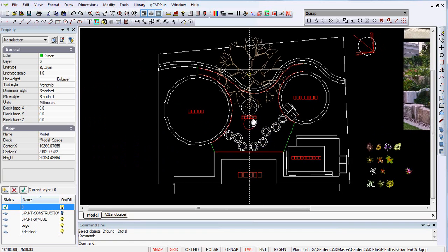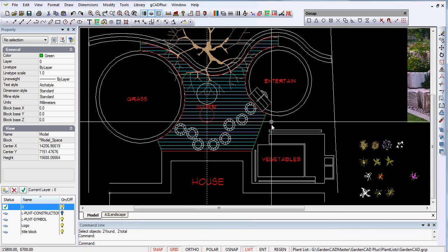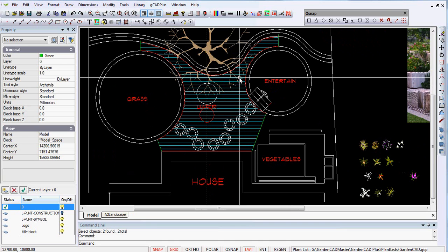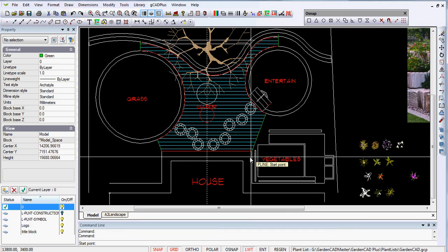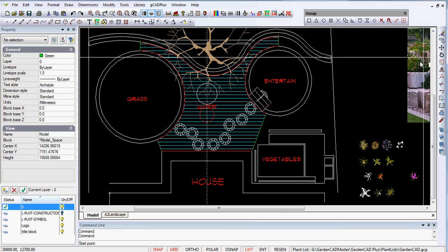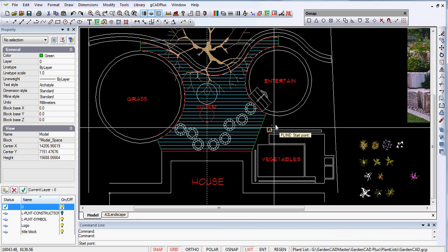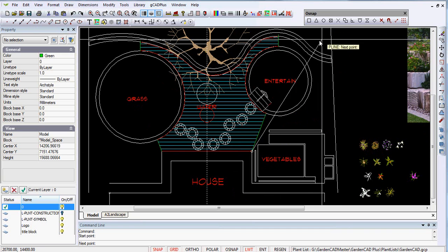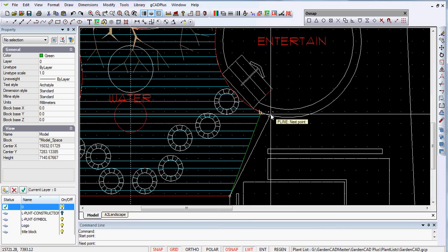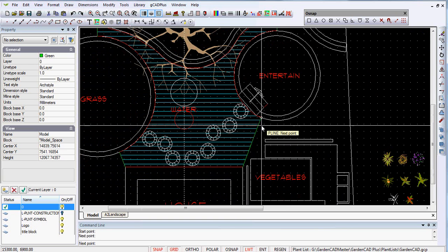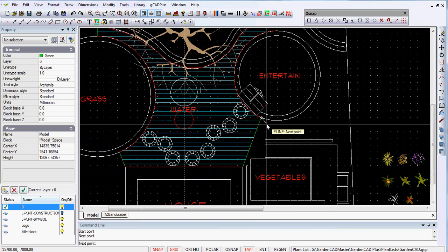So what we need to do is to create a polyline around that very complex shape. So how do we do it? We draw a polyline. Where are we going to start? We'll start at this point here, so we can use the entity snap end, and we go perpendicular to. I'll assume that my shapes are not there, perpendicular to the circle. So we've got the first of our polyline in.